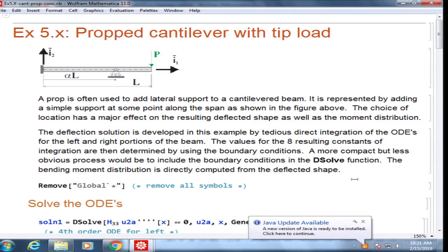So boundary conditions, I know that my moment is 0 at the right end. So I'll say my moment at L for part 2 is equal to 0. But my boundary conditions need to be in the form of displacements because my variables are displacements only, right? So what I'll do, I'll just expand its formula.